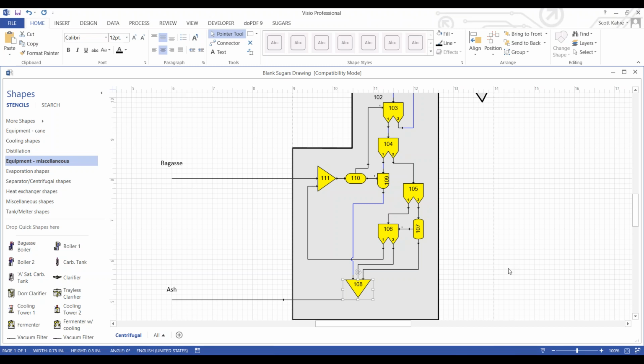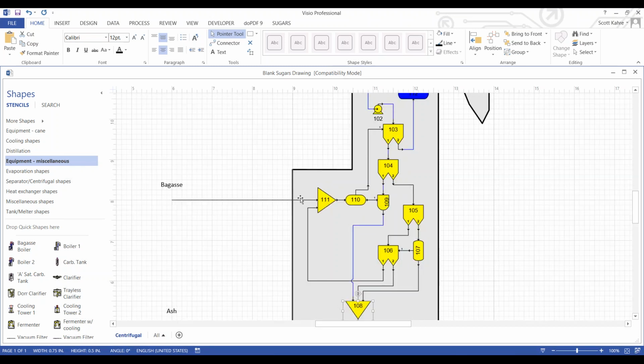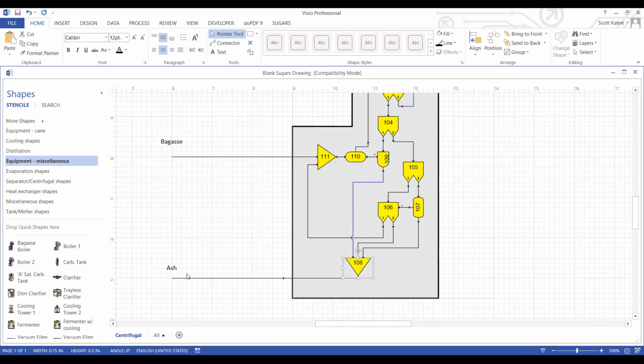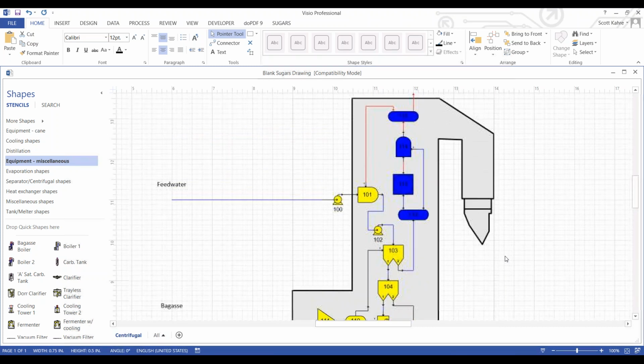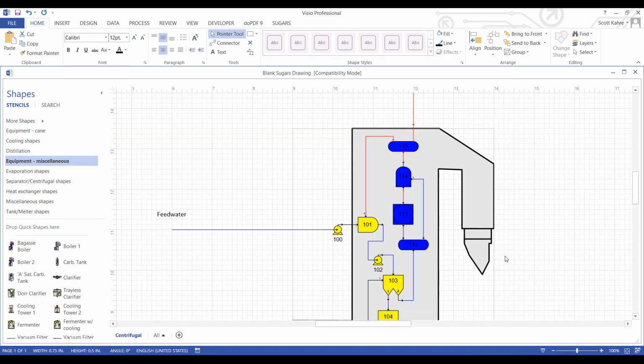All right. Now we have handled the bagasse all the way through from feed, ratio to steam flow, out to ash, okay? We still have to handle the steam side of the boiler because all the farther we got earlier was to the feed water and its ratio, or the bagasse flow ratio to the feed water. So the feed water was not separated or changed. It was just ratioed in this station 103. It came out output port number 2, and it goes on to distributor station 112.